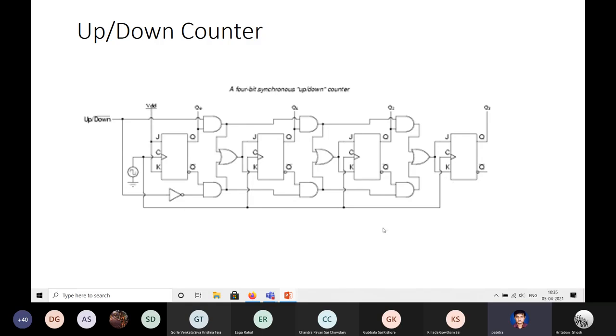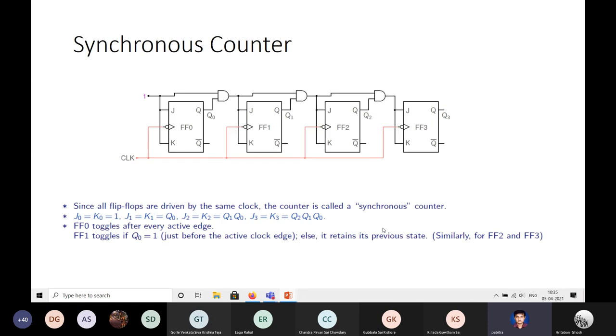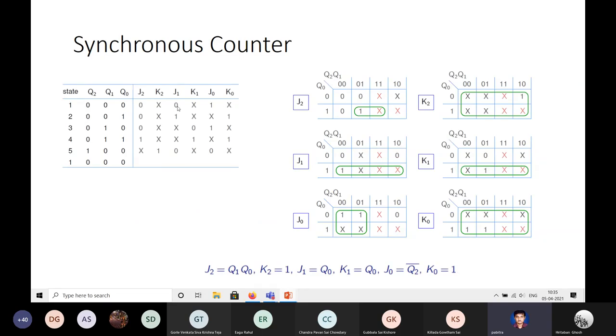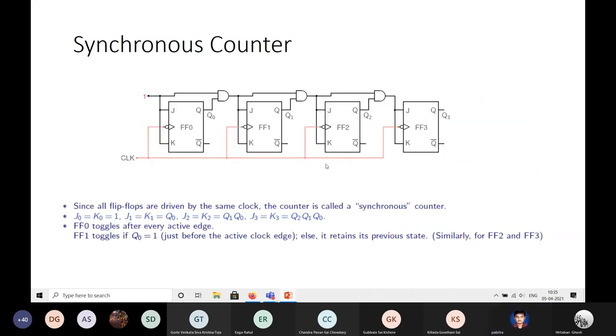And any other counter, a decade counter or any mod K counter, you can just design in a similar manner. You draw the transition table, and the activation function of a flip-flop ties Q2 to J2, K2, Q1 to J1, K1. According to the activation function of these transitions that you need, you write down J1, K1, J2, K2. Then you form individual Karnaugh maps involving each of these variables as output and Q2, Q1, Q0 as input. Get the thing? Wire them up accordingly.